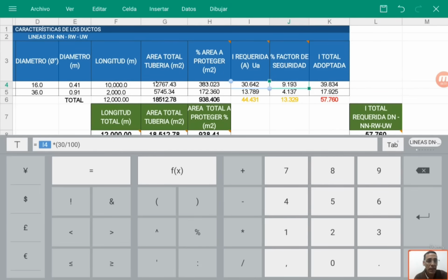If you end up short on exposed area or current density, that cushion might just save your engineering. So you should always take that safety factor into account, because what if you selected 3% but in reality it's 5? Then you'll need more current, and the safety factor is what can still support your engineering. The same thing happens with the required current. Maybe you calculated 35, but it turns out that in reality you needed 50 milliamps. So that safety factor is what can save your engineering work. So always stick to your point.